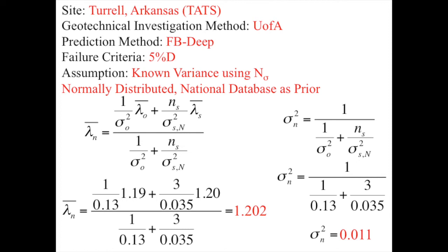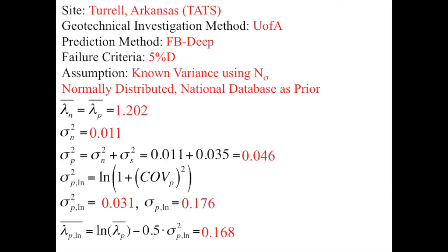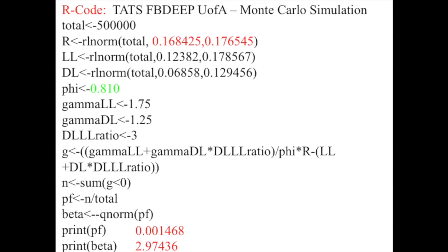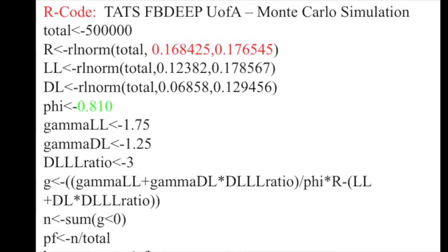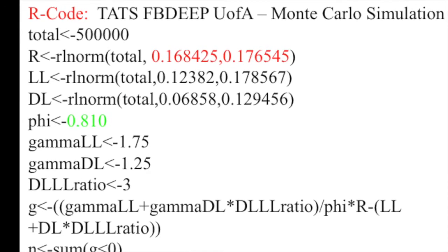The mean and variance values of 1.19 and 0.13 were obtained from Bayesian 2004. Due to the weighting, the mean and variance values from the predictive parameters of 0.168 and 0.031 were higher and lower than the values of 0.173 and 0.024 that were obtained from case 1a. Likewise, the resulting resistance factor that was obtained, 0.810, was lower than the value that was obtained from case 1a, 0.853.